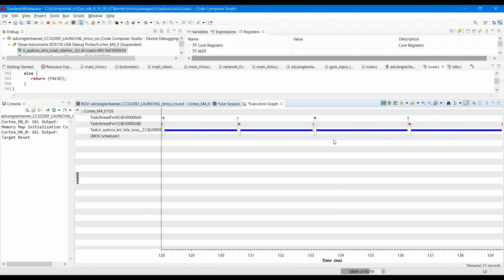So this is how the execution happens, and you can just reset the zoom and see how it is happening. It's very interesting. I leave this to you as an exercise to make some alterations in the thread functions. For say thread function 0, change it. Right now it is 12 for both cases. You can make one of them 6 and keep the other 12, and see how changing the time affects this particular execution analysis curve.